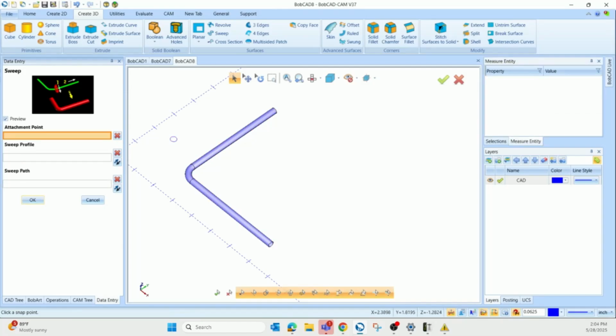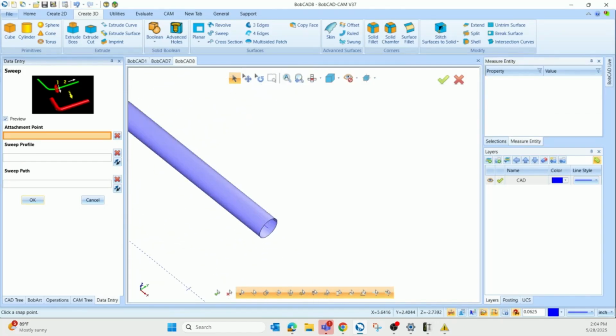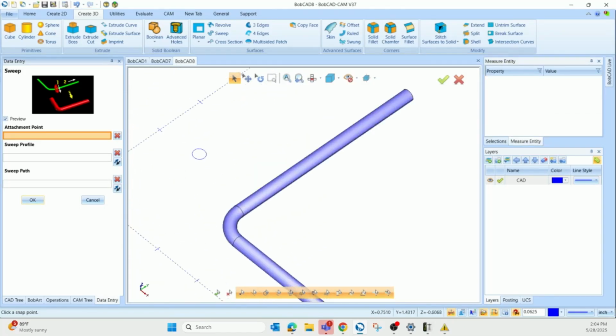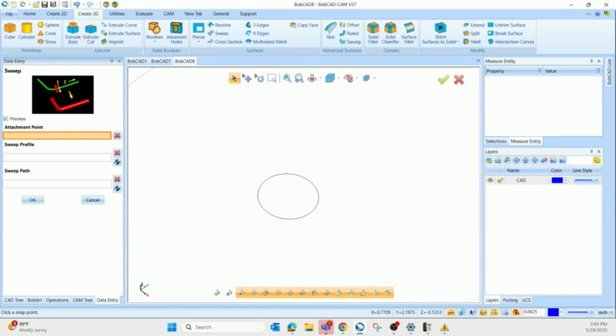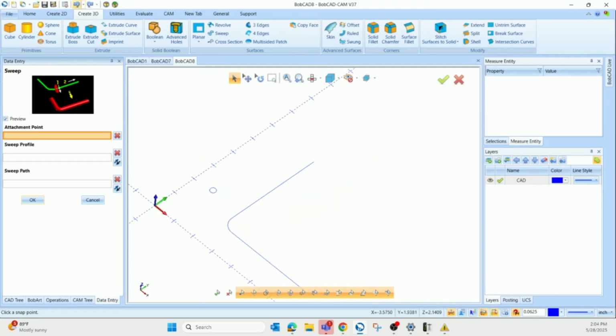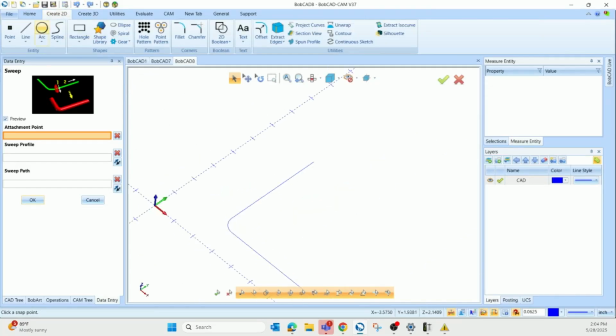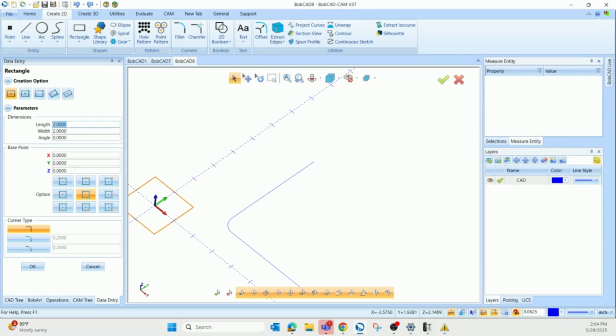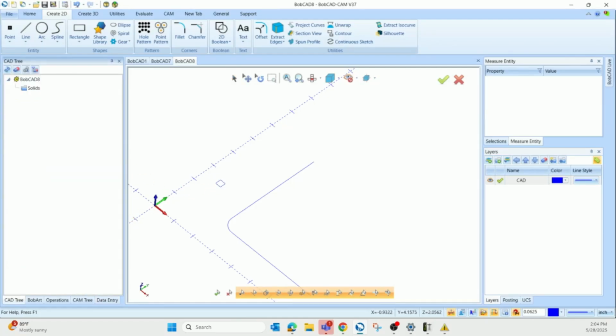And that's how you can create a shape like that. So you're sweeping a surface along a path that you've created with a closed chain, basically. I think, maybe let's do a square, right? I'm sure we could do a square here as well. Let's say 1/4 inch length, 1/4 inch width. And I'm going to put that square where the circle was.